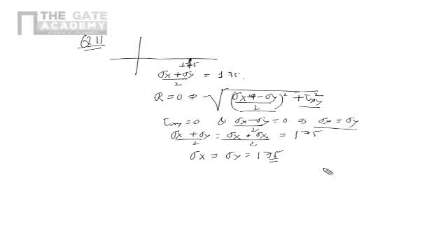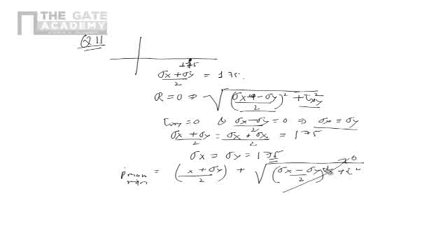That's the condition. So let us see what options are given. Determine the maximum and minimum principal stresses respectively from the Mohr's circle. Now what is the maximum principal stress? Sigma p max is (sigma x plus sigma y) by 2 plus, and we can write the formula for minimum also, it becomes minus, the square root of ((sigma x minus sigma y) by 2) square plus tau square. This whole thing is 0 because the Mohr's circle is a point, and we know that these values are both 175, because sigma x equal to sigma y equal to 175.